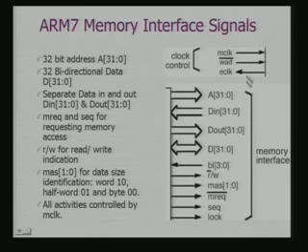Now, here you can find that the clock control has associated with it a signal called wait bar. This is an active low signal. In fact, your internal clock for the processor core is actually a combination of the two. And how and where to use this wait signal? If you remember, I said that in many cases my memory may be slow.